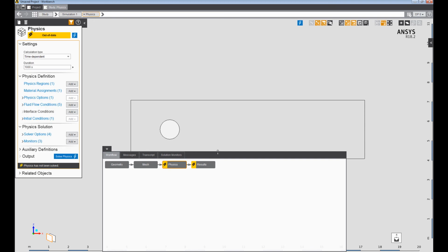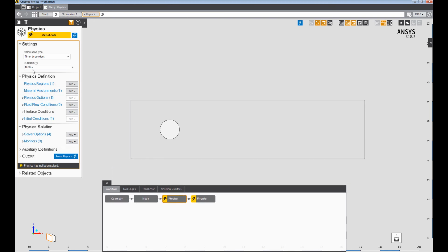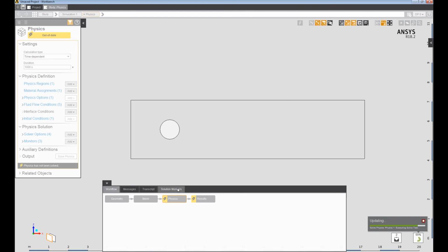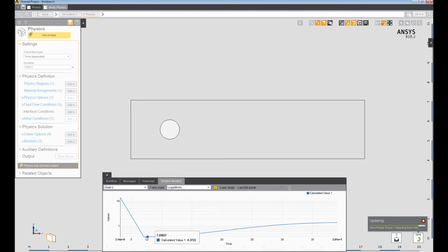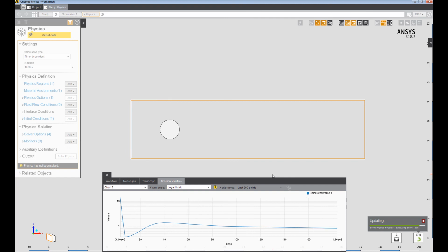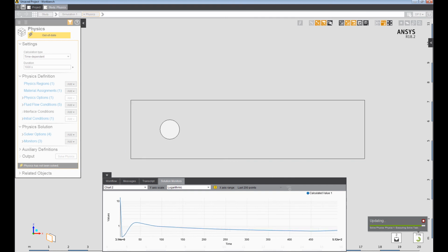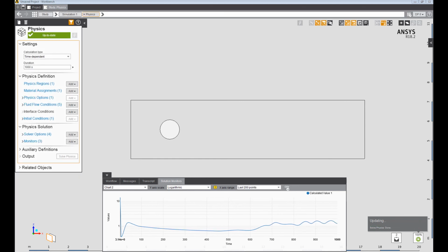The default transient solver inside ANSYS AIM is a huge improvement over the previous techniques available. Previously, users had to manually assign a time step, trying to manually balance between the speed of the simulation as well as convergence and accuracy. ANSYS AIM uses truncation errors to decide on the optimal time step, and it continually modifies that throughout the simulation to ensure that transient effects are captured and the accuracy of the simulation is preserved.